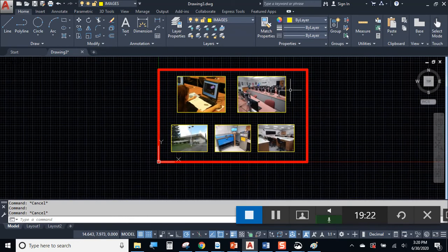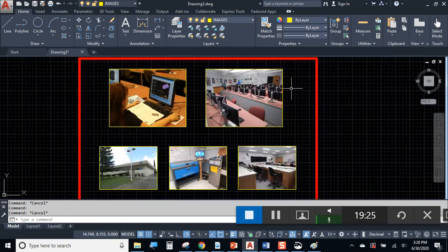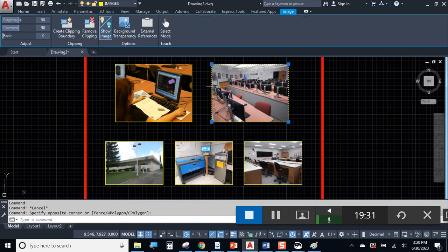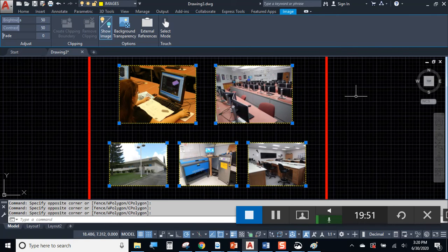So there's an advantage to doing this, and it's this. CAD files are supposed to be small. If we started attaching images to CAD files, they would start ballooning in size very quickly, because raster data, especially for these megapixel pictures we take on our cameras now, raster data is bloated and enormous compared to vector data. So to keep the CAD file small, AutoCAD doesn't actually stick the picture in the drawing. It just sticks a viewport or a window or a TV screen that lets you see the picture.